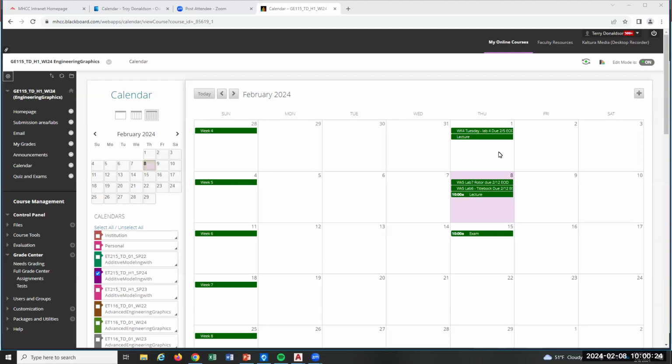So some of us are struggling with hidden lines still. I went through all the labs. Sometimes they don't show up on the PDF, so we have to make that happen in Paperspace. Some of us are still struggling with the text height with dimensioning. So if you're struggling with that, you got to get with me or ask a question, something, figure it out, right? Because that's what we want full control over for the exam.